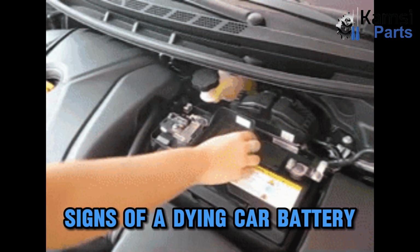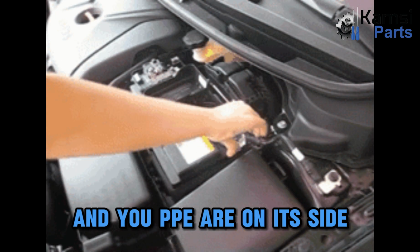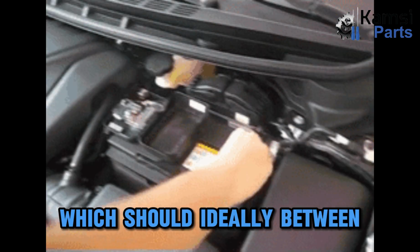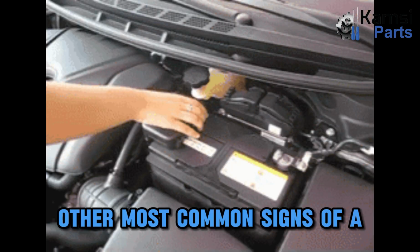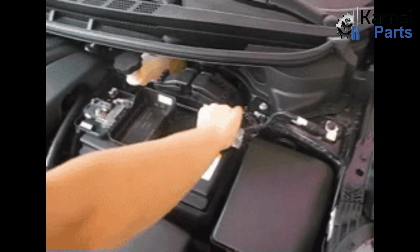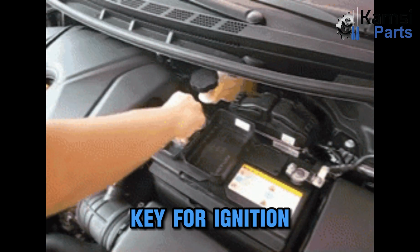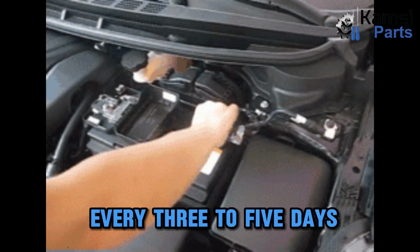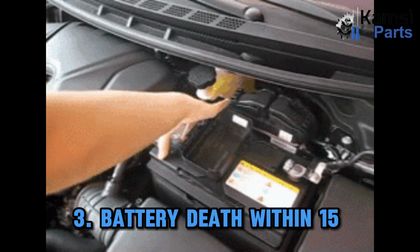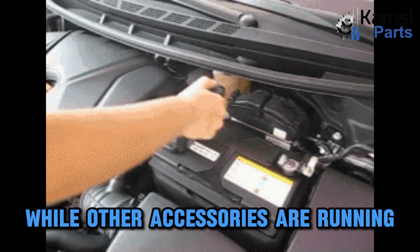Signs of a dying car battery. If your vehicle has a battery marked with lower and upper marks on its side, you can check the electrolyte level, which should ideally be between the lower and upper mark. Other most common signs of a dying car battery include, before startup: 1. The gauges and lights don't turn on when you turn the key for ignition. 2. Jumping your battery every 3 to 5 days or even more frequently. 3. Battery death within 15 to 30 minutes of idling with the engine off while other accessories are running.